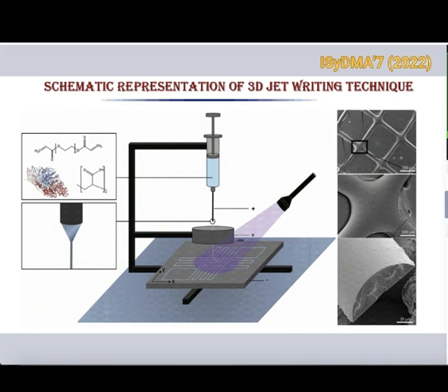This is a combined technology which is called 3D jet writing, electrojetting, and also called electrospinning writing. This method in principle is described as a modified electrospinning process which produces 3D structures with unprecedented precision and resolution, thereby offering customizable pore geometries and scalability down to several millimeters. The polymeric liquid droplets at the needle tip are deformed and are accelerated towards the collector electrode in the presence of a high applied electric field in a conical fashion.